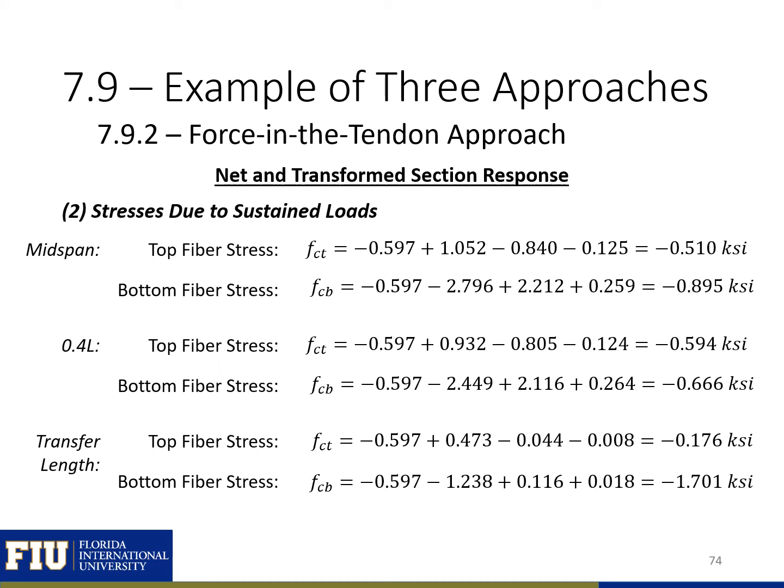Using the equations on the previous slide with all of our known values, we can calculate our top and bottom fiber stresses at our 3 points of interest. And we can compare these stresses against our ACI 318 stress checks for pre-stressing plus all of our sustained loads.